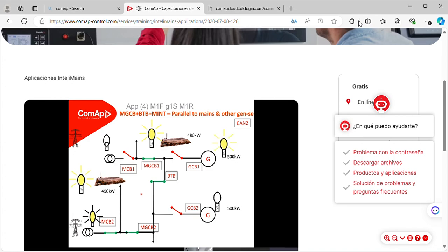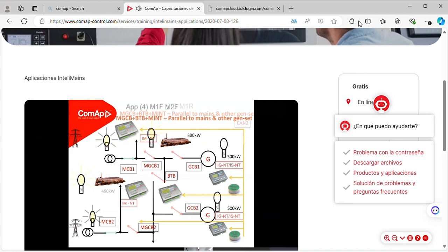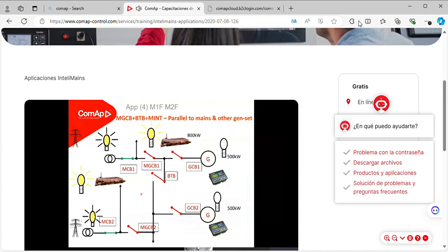If the load further increases and you do not want to take enough power from the utility, you can even perform standard base load operation or import export operation, and you can load share between the utility system. Once my other utility is back, I can synchronize and go back on standby. This was under one utility failure. But the second scenario is where both utility systems fail, or when you do an annual shutdown kind of sequence to emulate overall system behavior, what happens when a complete substation failure happens.